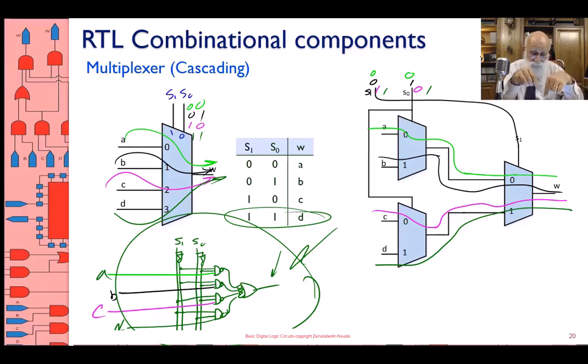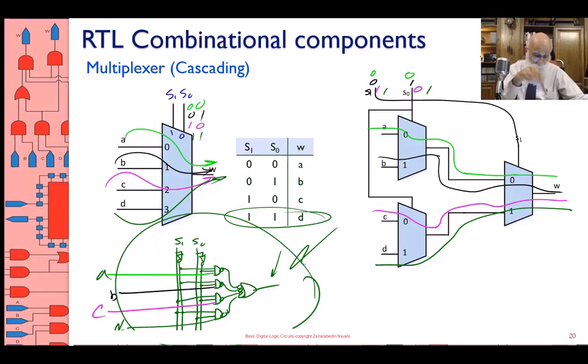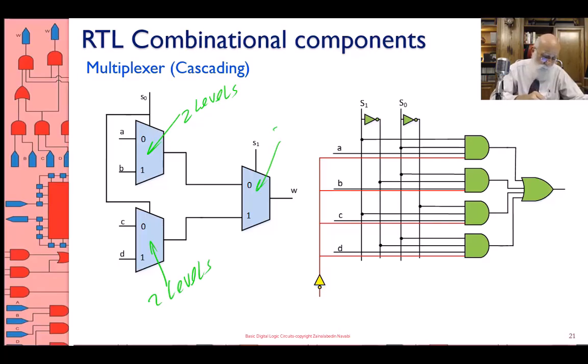So what I want you to do is compare what I have here with what you would get if you take these circuits, 3 of these, cascade them like this, whereas if you do the straight NAND gate implementation, which is actually this. Comparing these two, here I have 2 logic levels and ORs, 2 logic levels, and then 2 logic levels here.